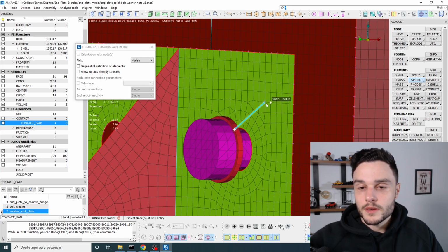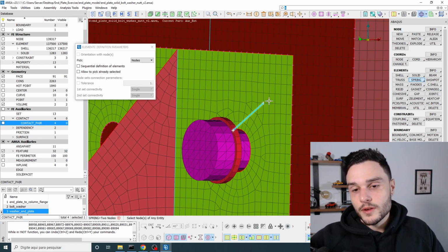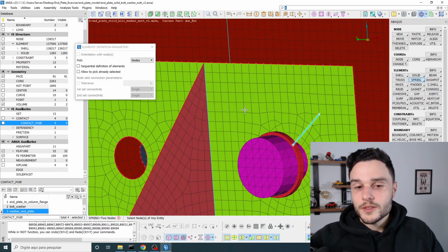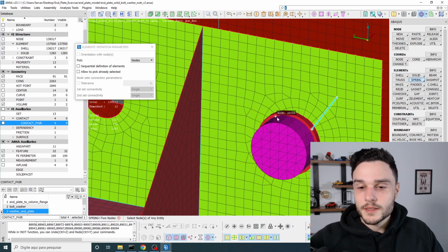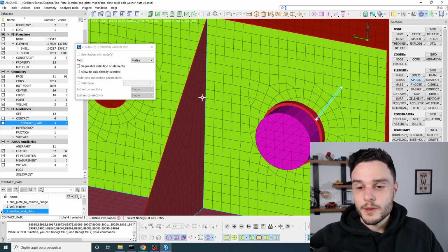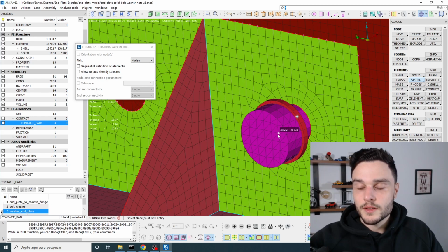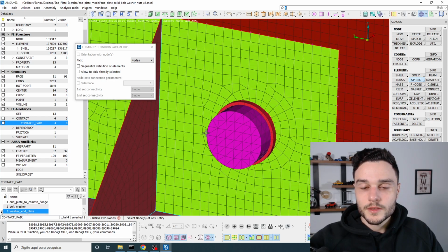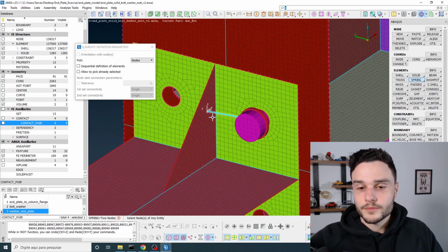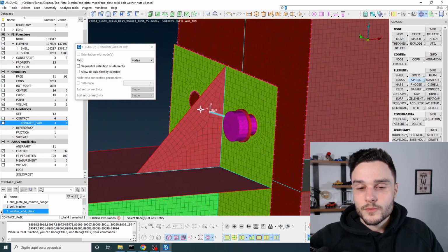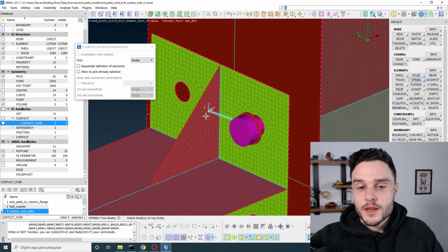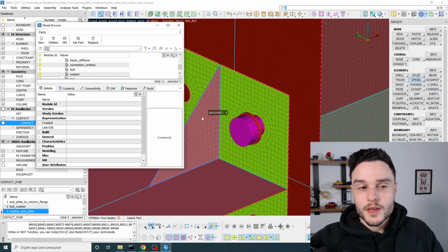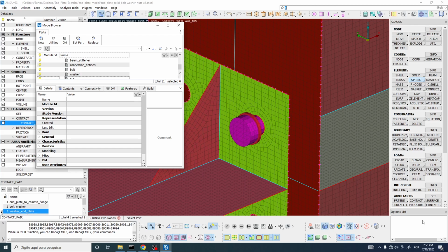This part of the end plate surface is related. Well, we do have contact here actually. So maybe instead we can connect this washer to this stiffener. Maybe it's a better idea. So I'm going to right click here to deselect this node and then also this one. And I'm going to select one node here to connect here. Okay, middle mouse button. And then, by the way, I guess that in this part of the screen we can just put it in auxiliary entities.